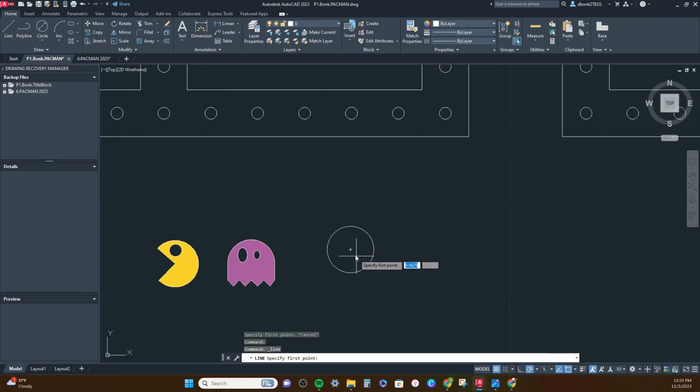Turn the line on, go to the center point, and start drawing an angle for the mouth. And just hit escape, draw the line, draw the line again, draw another line. We're going to trim away what you don't need. Trim, if you hold the mouse down while you're trimming, you can just draw lines like that through. Do another center point circle for an eye. You're going to make the eyeball relatively large when you're zoomed out. It's not going to look that big, but you could just freehand the size of that.